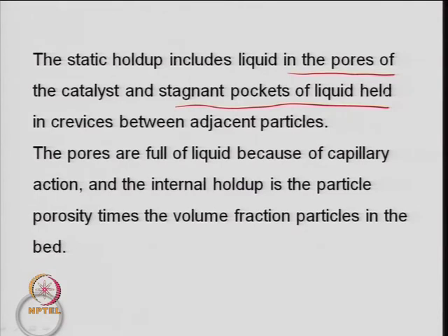This is again important, because when you write a kinetic expression, you write the rate proportional to the concentration of the gas and the concentration of the liquid, and we correlate that based on the concentration available in the bulk. What is important here is that the pore of a solid is already saturated by the liquid, and the gas diffuses through that and reacts with the liquid, and then the product comes out, and again the liquid penetrates into the pore. So, all the time the liquid is saturated. One can say there is a high concentration of liquid compared to gas.